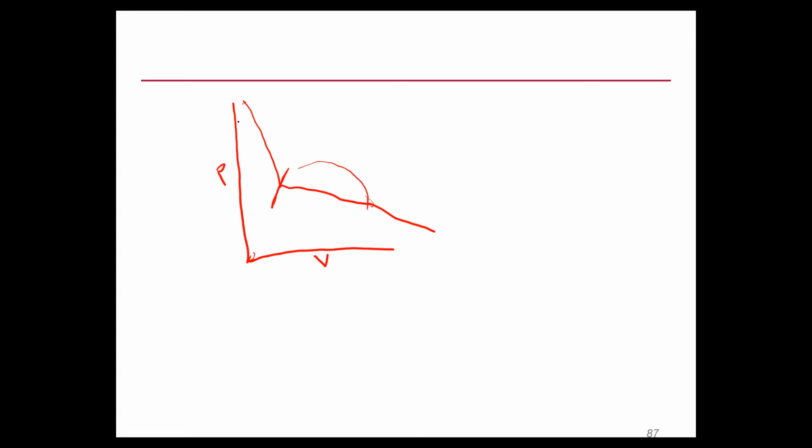We can do this test at different temperatures. It will be something like this. We call this section single phase oil. We call it depletion. You haven't reached the bubble point yet. You see it expanding. When it is expanding, the distance between wax, asphaltene and resin is increased.